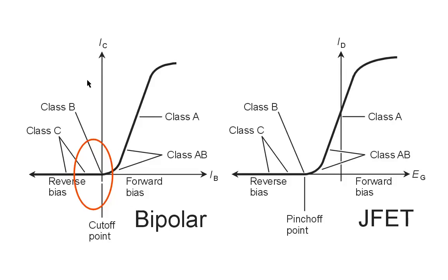Frequency shift and phase shift keying will also work with Class C, but AM, old-fashioned amplitude modulation, you don't want to use Class C as a radio frequency power amplifier for that particular mode, nor single sideband. You don't want to use a Class C amplifier in an attempt to make a power amplifier work for single sideband. So that's basically the situation here with classes A, AB1, AB2, B, and C, in particular in regards to radio frequency power amplifiers.